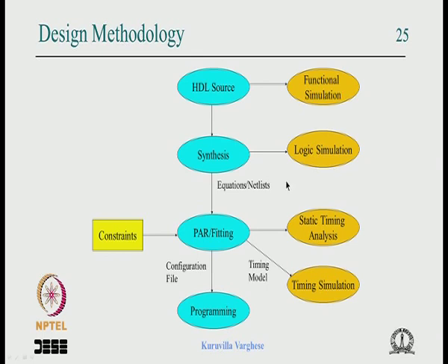So you give to an AND gate A and B at 10 nanosecond, the Y which is the output comes out at the 10 nanosecond. Okay. So no logic delay or interconnect delay, so there is no delay here. But mind you, here you are simulating the code, here you are simulating the circuit without delay, and if you find errors, if there are synthesis errors, then you can go back and iterate.